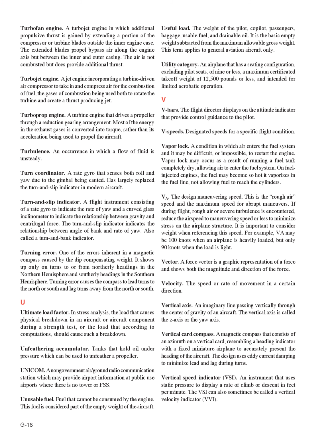Vapor lock. A condition in which air enters the fuel system and it may be difficult, or impossible, to restart the engine. Vapor lock may occur as a result of running a fuel tank completely dry, allowing air to enter the fuel system. On fuel-injected engines, the fuel may become so hot it vaporizes in the fuel line, not allowing fuel to reach the cylinders.